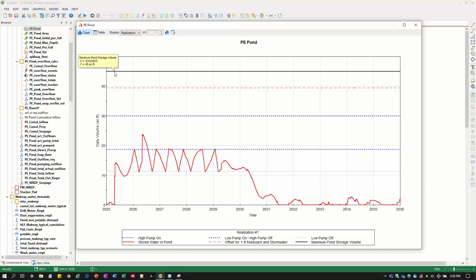If you put even just a drop more water, it's going to spill over. This line down here is how far you want to fill the coffee cup to feel comfortable, right? So an engineering design will often have a foot of freeboard, 2 foot of freeboard, and then maybe some stormwater consideration to offset in our pond. So that's this line, kind of our indicator that, hey, you're getting too full.